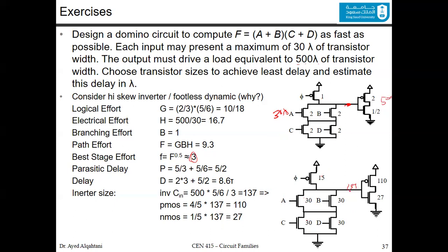Now distribute that 137 among those 2 based on what you have in the original sizing. So what you do is you say, okay, I have in the PMOS, give myself more space. In the PMOS, you have 137 times the summation of those 2, which is 2.5.